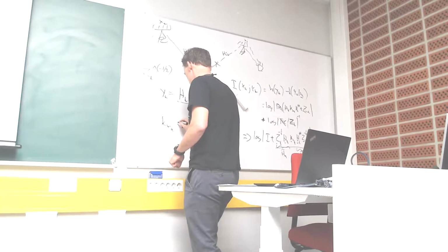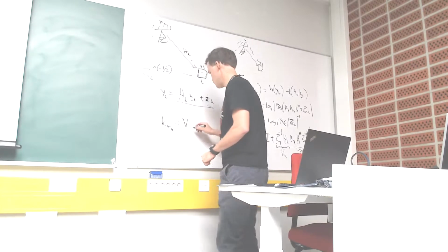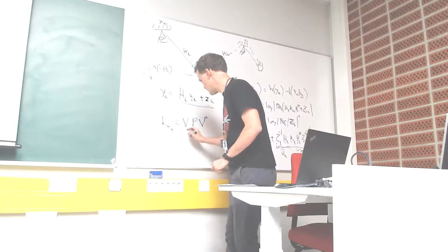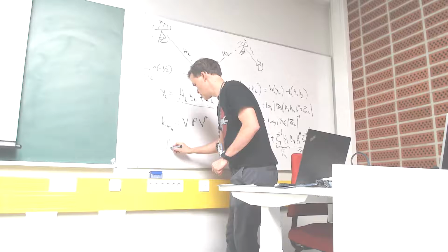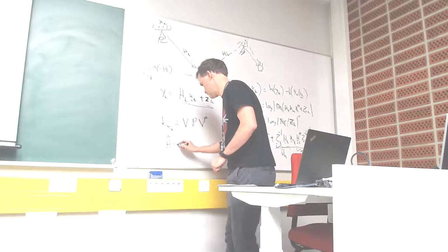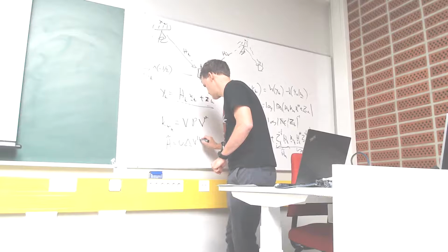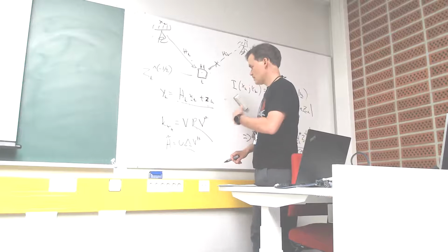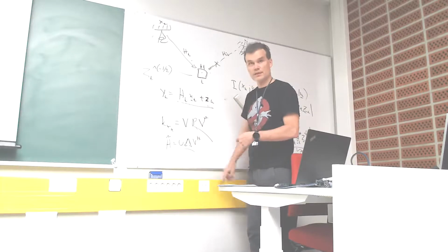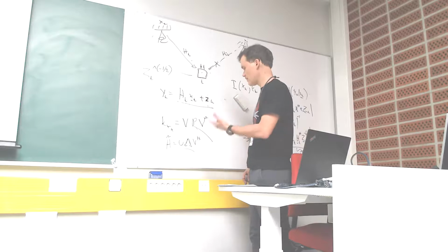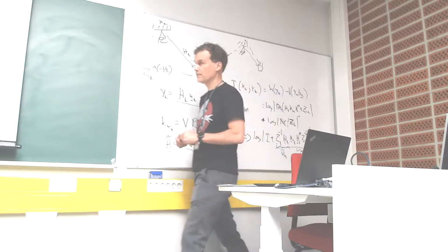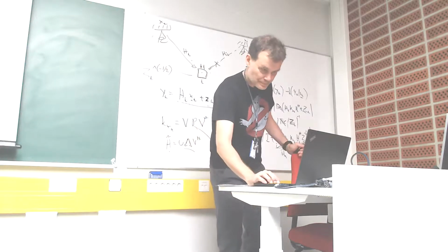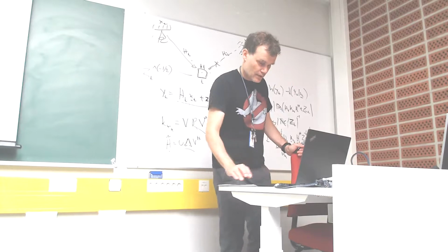We can split KXK into V P V Hermitian, where V is the right singular vector of this whitened matrix, and this P is found by water filling over the singular values of the whitened matrix H tilde. So quite straightforward.